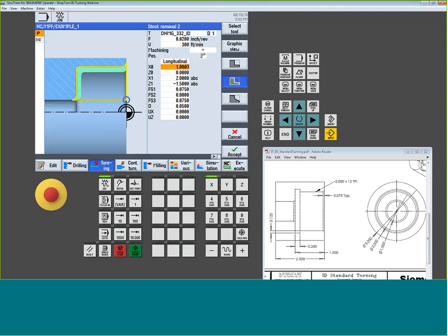And then we start to fill out our movement. So our starting diameter, before we're used to working from the outside coming in, now it's opposite. So I'm probably going to give it what my hole size is, in this case 1 inch. Where is the face of the part? It happens to be 0. Where am I ending? I'm ending at a 2-inch diameter, or potentially, if I knew what the true thread diameter would be, something slightly less, but that's fine.